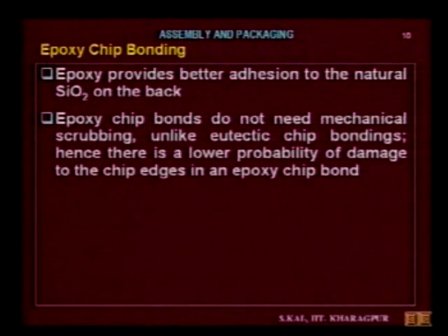As this epoxy chip bonding technique does not require scrubbing, it is better as far as damage formation is concerned compared to eutectic chip bonding.